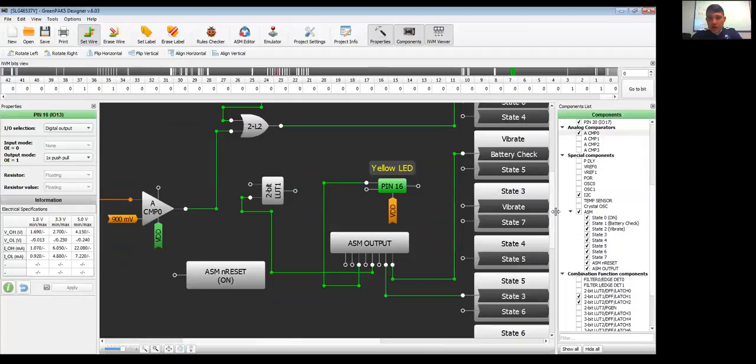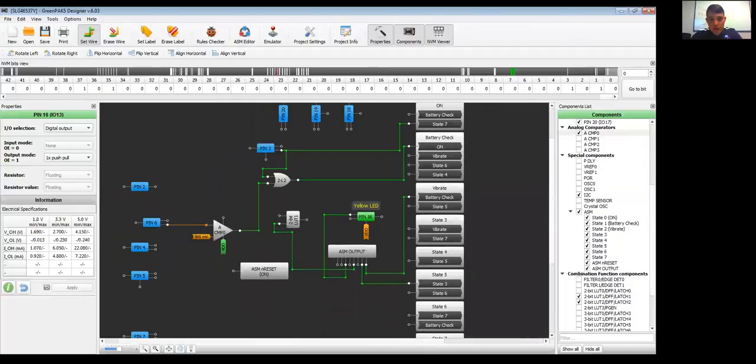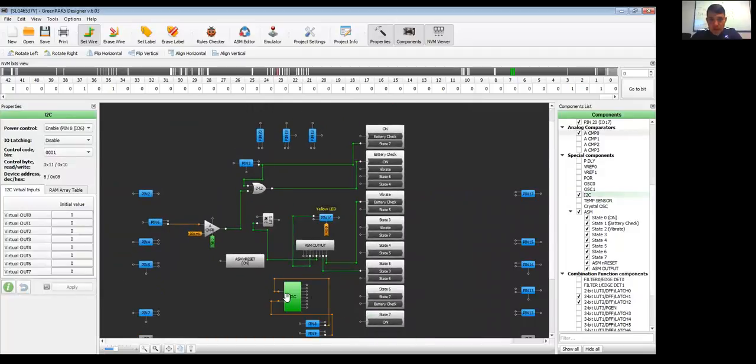Now we're also coming out with our 6th generation GPAK, which will have a richer asynchronous state machine in it, and have up to 12 states and far more logic associated with it. And instead of just having 20 pins, it's going to have up to 32 pins. We'll also have smaller versions of that one as well.